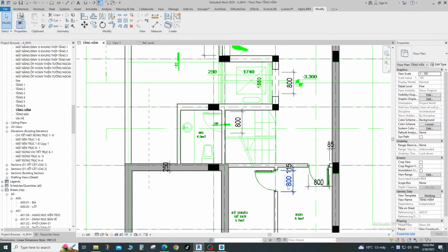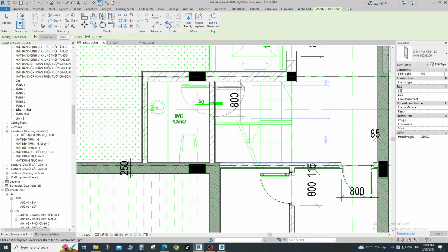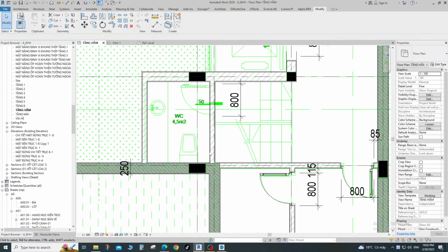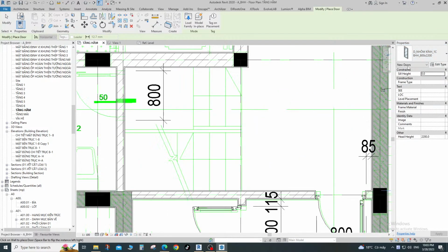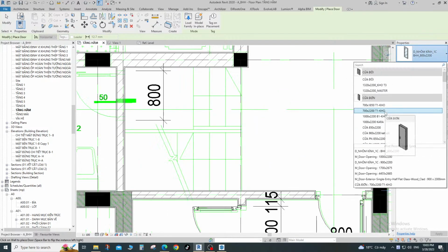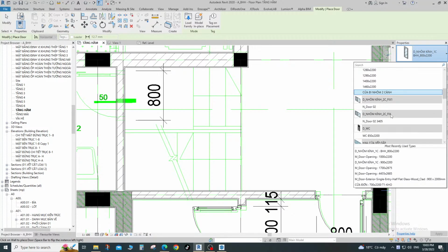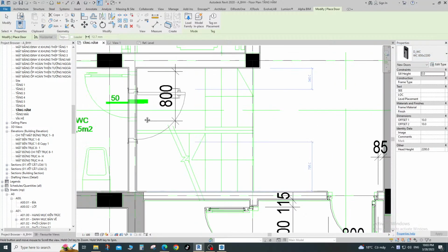Okay, so now let's create a stairs. Go to stairs, and first change the level. The base level is ground floor, which is correct. You can see this one goes up and turns 90 degree, going up to level 2. So change this to level 2.